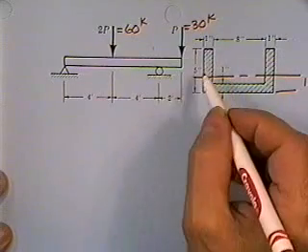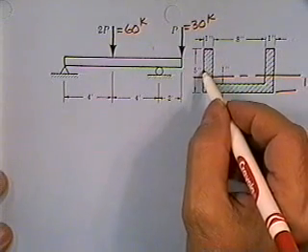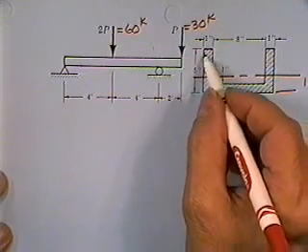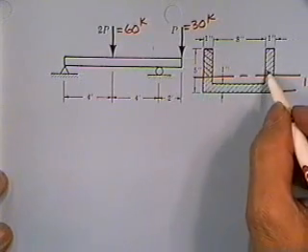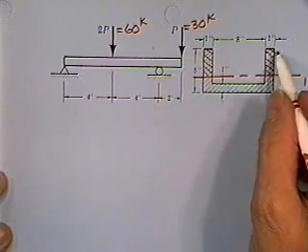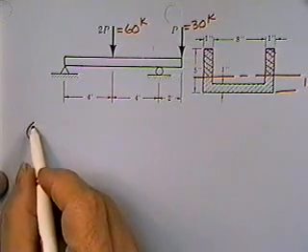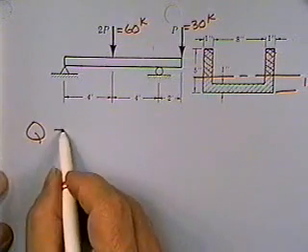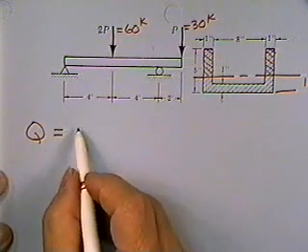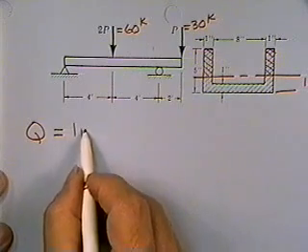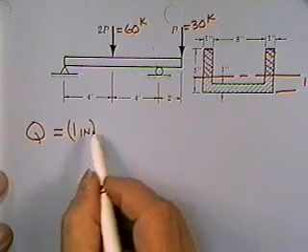Q is the one we're kind of interested in. Here's how you'd get Q. You would crosshatch everything above the neutral axis. That would include two areas. You would then solve for Q, which equals a 1 inch thick piece that has been crosshatched.